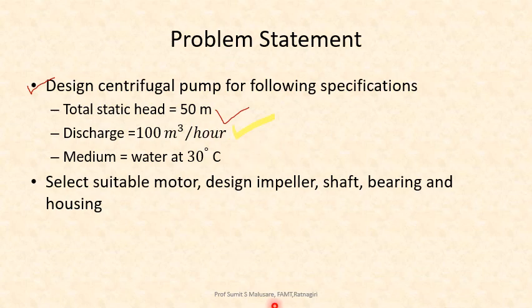Now what kind of variation is made possible over there? Instead of 50 meters there may be 10 meters, maybe 20 meters. Here the total static head is given. In some numericals the static head may be given separately, say 2 meters plus delivery head of 8 meters. Likewise the split up is also given. So according to the given data, start with the design.